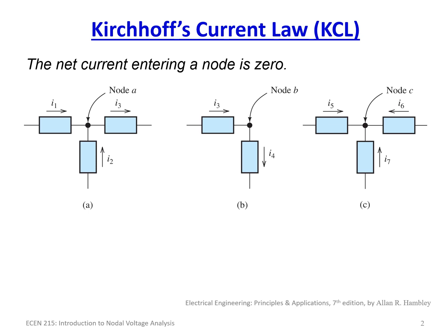And notice we have node A, node B, and node C. And it's just where the 3 circuit elements come together. And we've labeled our currents, that was when we were talking about current and voltages the other day. We have an arrow, and we have simply that the current is flowing in the direction of the arrow. So if the current here was 5 amps, that means 5 amps is flowing this direction. And if the current is minus 5 amps, using this convention, that means the current is actually flowing in that direction.